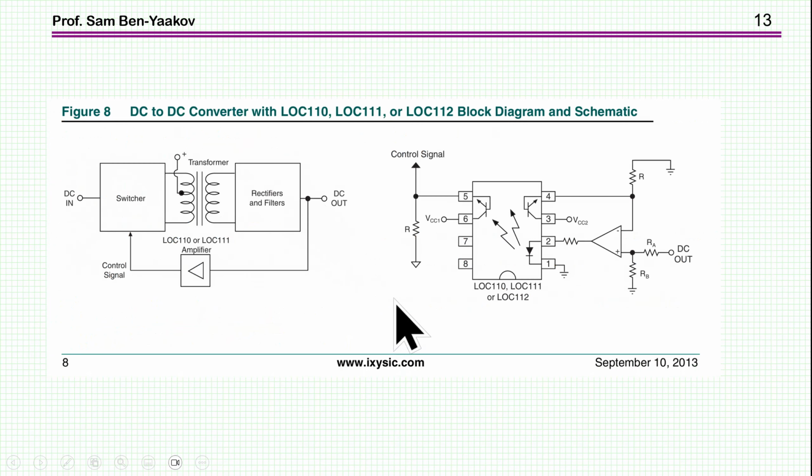Now, some of the companies in their application notes, like IXYS, which I guess is now Littelfuse, and other companies are showing something similar, showing how you can use this particular unit, the linear amplifier, as feedback in a power supply. Okay, so here we have an isolated power supply. We have two grounds here. We have an output, and then we have here this isolated amplifier. Now they are showing it in a different way, where the output has no amplifier, just the diode and a resistor without buffering with an operational amplifier, which is okay if it goes into high impedance.